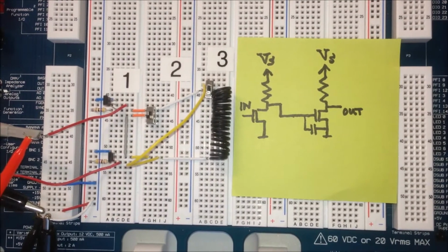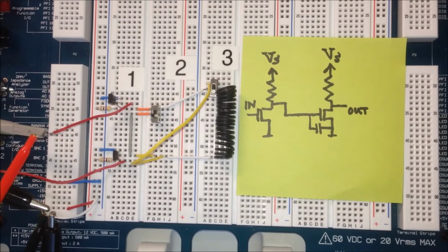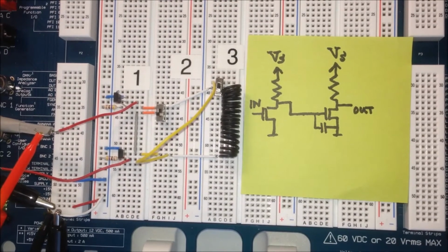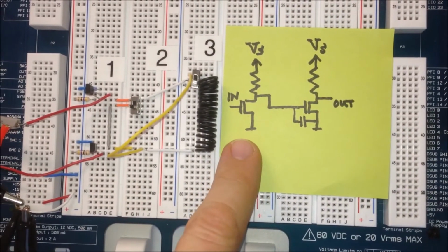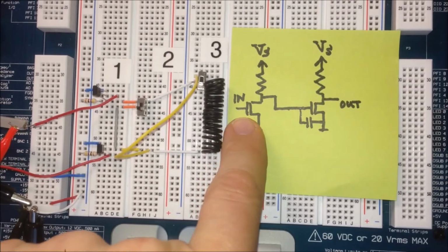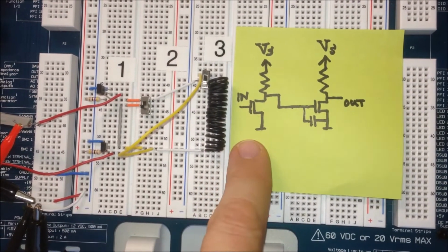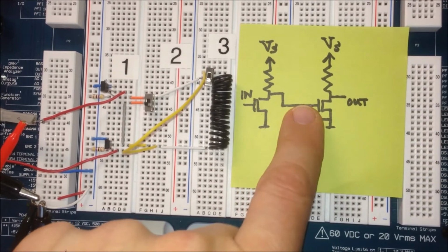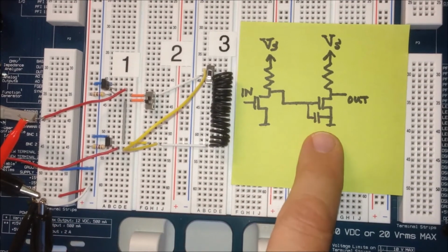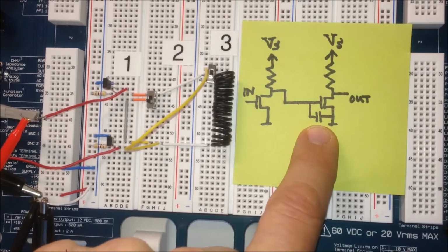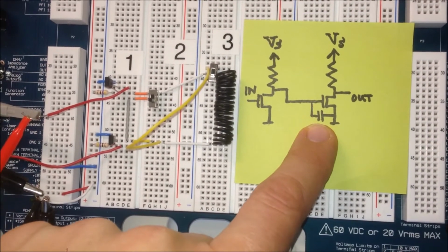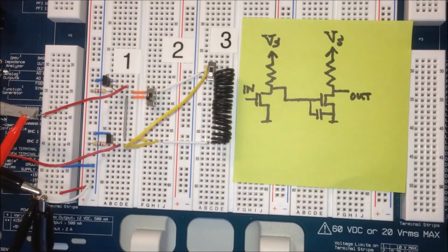Okay, so we're going to do a little demonstration here of the effect of inductance. And we've built a little circuit based on two MOSFETs. So the signal comes into the first MOSFET and then gets amplified and then is driven into the second MOSFET. Now we have to be aware that there are little capacitors that are intrinsic to the gates of the MOSFET. This is the gate source capacitance.